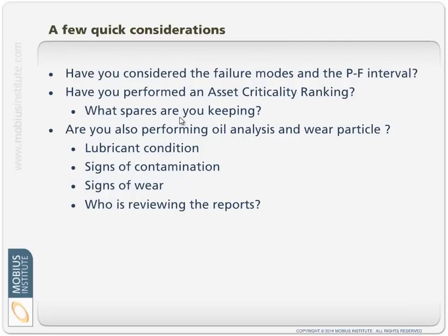And as part of all of that, because you have to take all of these readings, that has a cost associated with it. We may also do wear particle analysis and oil analysis. We really should be performing those condition monitoring techniques, and that's where the asset criticality ranking is important, to understand the criticality of the gearbox, which therefore justifies what effort, what investment you make to monitor that gearbox.